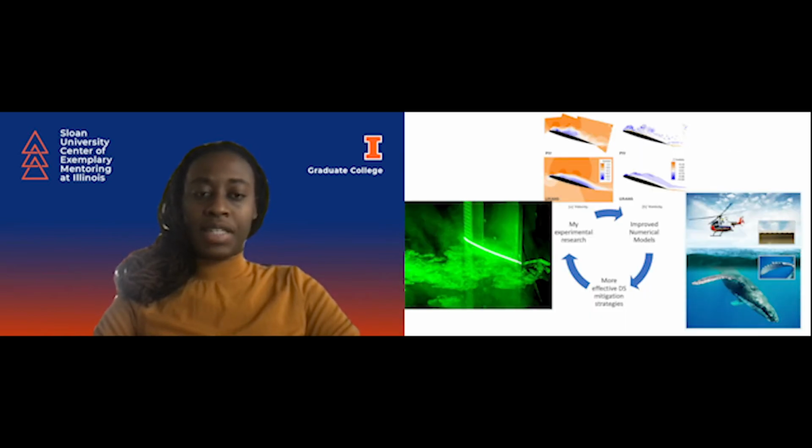As can be seen on the second slide, my primary research area focuses on experimental work. That experimental work allowed me to perform experiments on the airfoil inside a wind tunnel and be able to characterize the flow within the dynamic stall process by pitching an airfoil really rapidly in the wind tunnel. That action of acquiring data allows us to improve numerical models and to eventually lead to more effective dynamic stall mitigation strategies by controlling the flow around such wings or wind turbine blades.